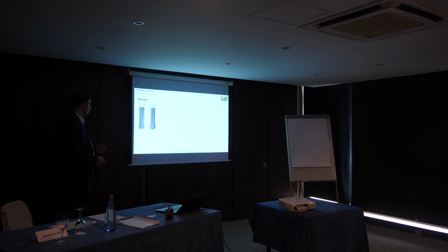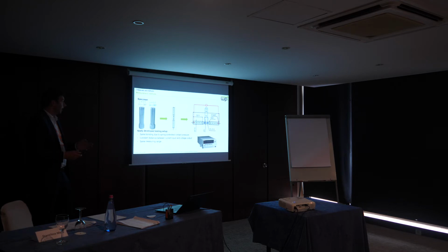So we took this part with 30 and 90 degrees and took a specimen out of it with this geometry, and I applied a newly developed test setup where I developed a spring-controlled contact to have always the same contact pressure, because the contact pressure is a really big influence on the measurement of electrical resistance.